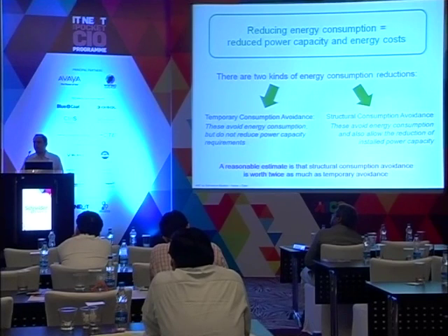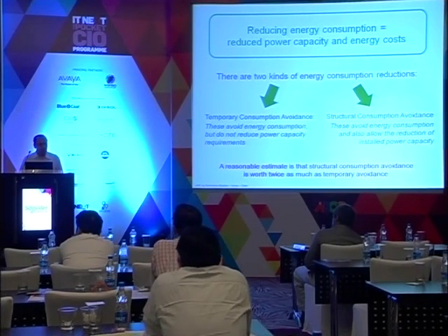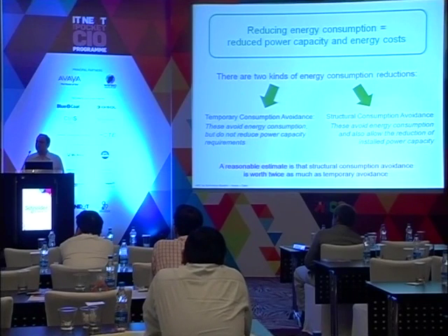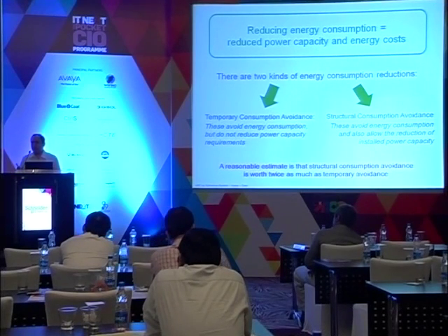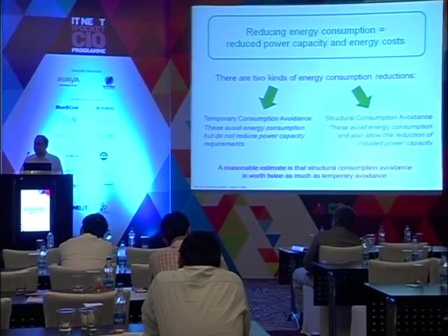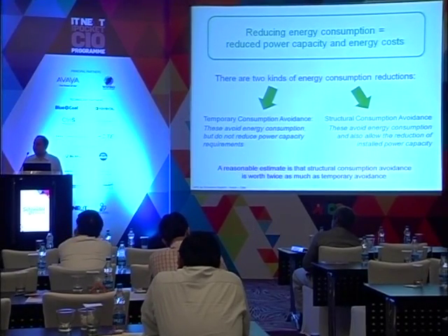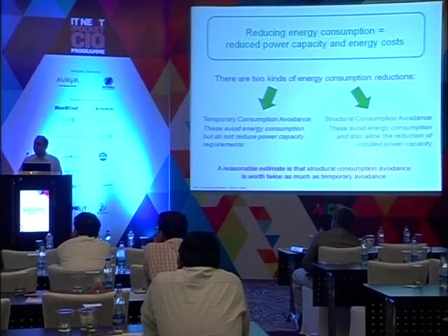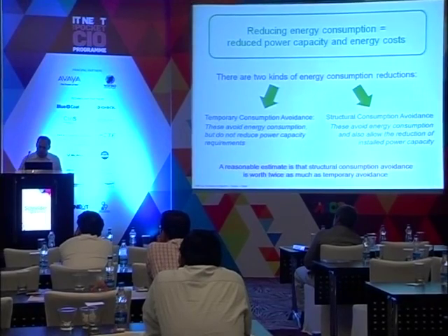First example would be to make a data center infrastructure modular, so that when you know that your data center is only loaded to up to 40% of IT load, you should be able to shut down certain modules, for example UPS systems, for example chillers, etc., which anyway you don't require because of the capacity, right? So this is what is called a structural avoidance. So structurally your data center is capable of modulating its capacity to meet the requirement posed by IT equipment and thus helping you make it more efficient.